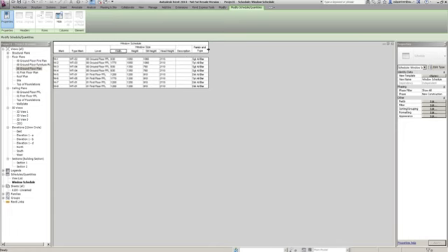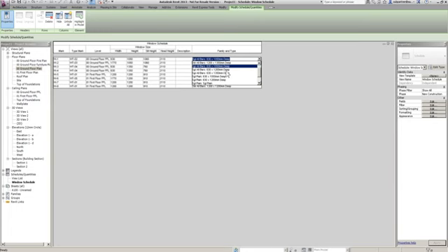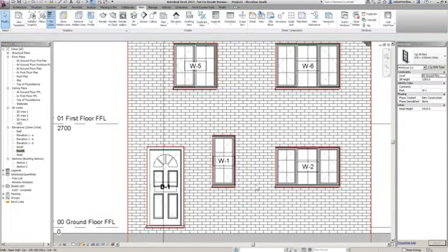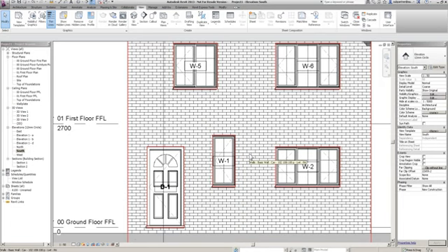For example, okay, if I just extend this, that's my WC, this one here is in, I remember that. Okay, I can go into here and I can change the window. I can change it to whatever one I want. I'm going to change to a 1350 deep one. Okay, this information here will change. Just look what's happened. My head height changes. Okay, let's go to my south elevation to look at this. Yeah, a little glitch that happens with the standard windows that come with the library. What happens is when you change the height, the sill stays where it is instead of the height.